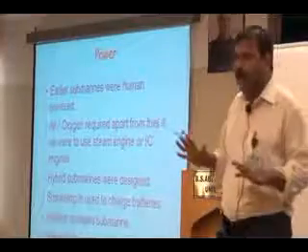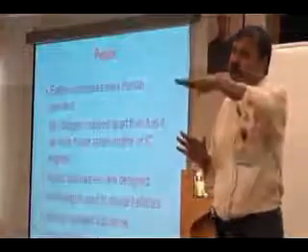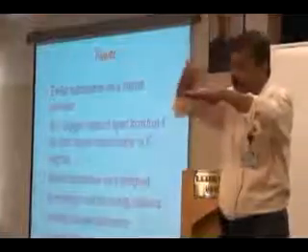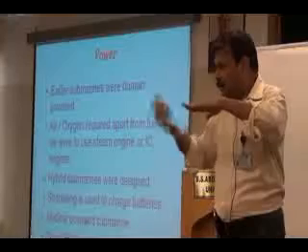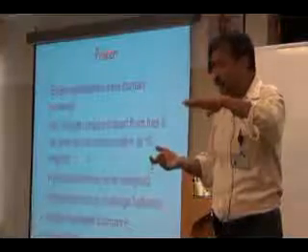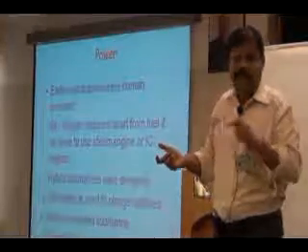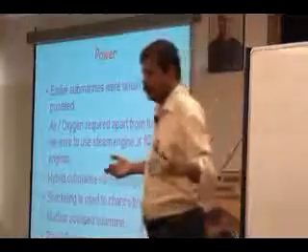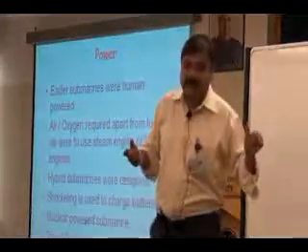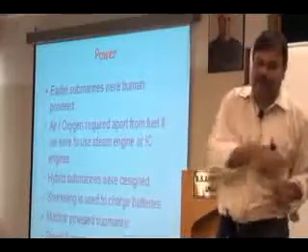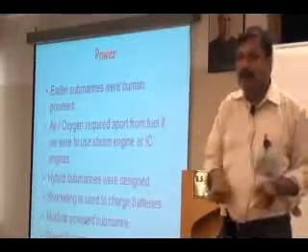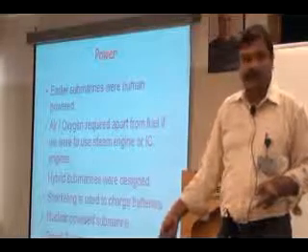Now what the submarine will do is, it will come just below the water level, take air from the atmosphere, run its diesel engines, then charge batteries. These diesel engines will run a generator and charge the batteries. So all the batteries will be charged. Then it can go to the depth. Now from the batteries, there will be electrical motors that are driving the submarine.